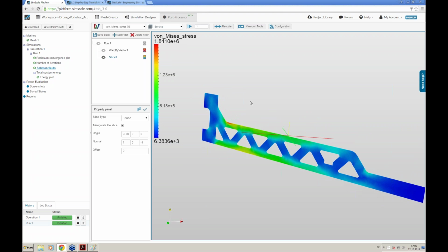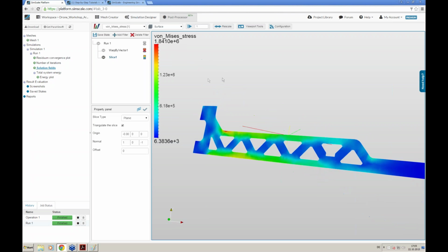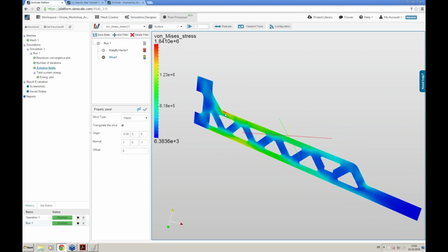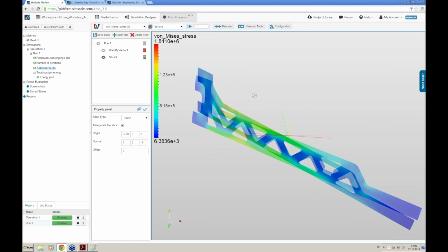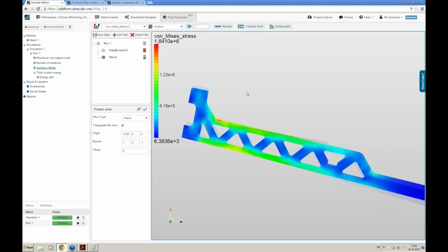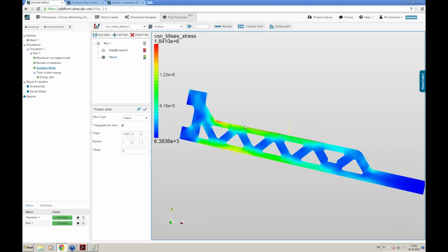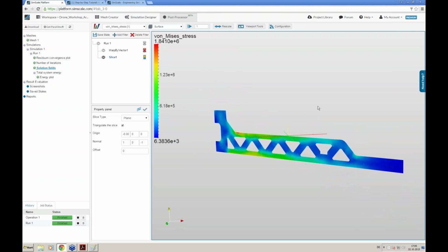And then you can also check the maximum stress, which is the maximum elastic stress of the material. If it's higher than this value, then you know it will break there or deform plastically. Yes, and that was our simulation.